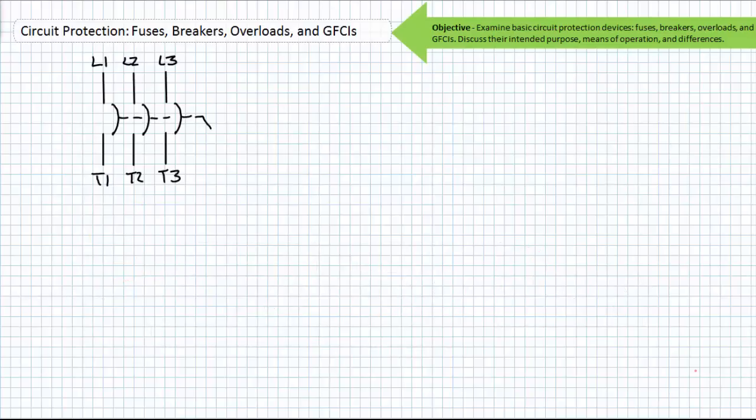Before we move on to our next protection device, consider again the means of operation and purpose of a circuit breaker. It protects the system from high current. It does not protect an operator from small levels of leakage current. The only way a 20 amp circuit breaker will open is if it is manually opened or automatically tripped when an excess of 20 amperes of current is traveling through it.